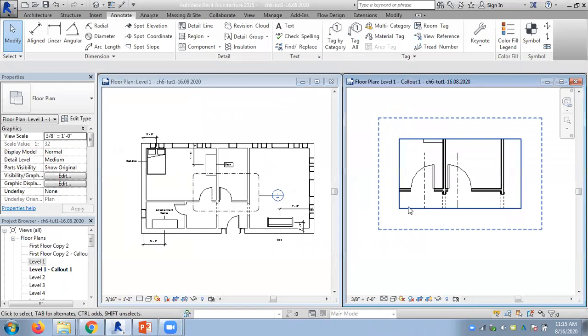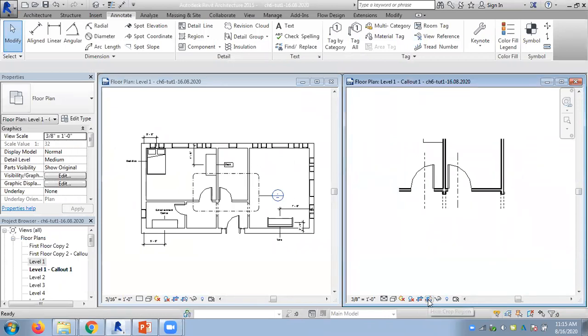And here you can see there's a boundary coming around the drawing. So if you want, you can switch off that boundary. There's a tool called show crop region, hide crop region. So this is like the Windows picture cropping. So you can hide the region as well as you can say do not crop it.